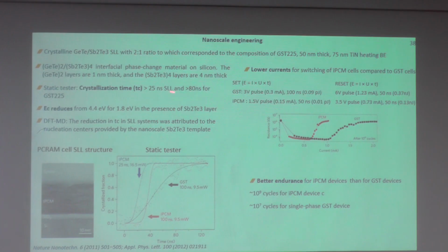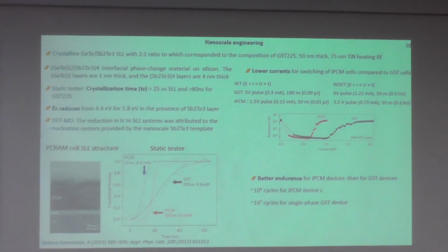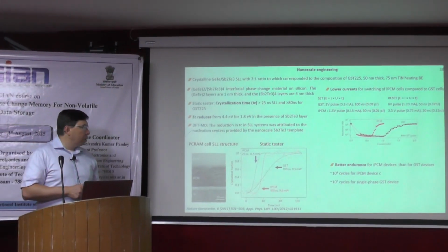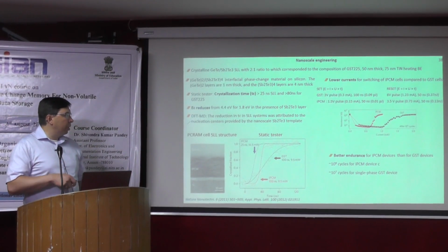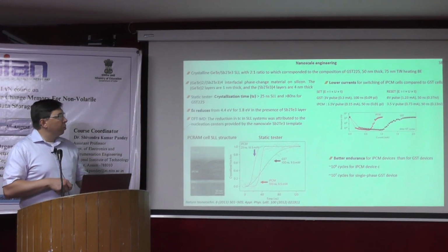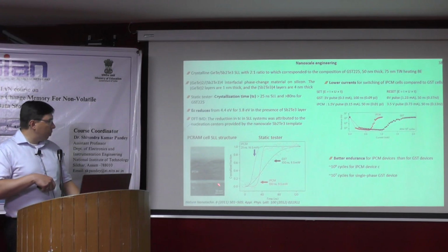The crystallization time is lower than that of GST225, but still on a nanosecond time scale and not sub-nanosecond. But here we can reduce the energy consumption. Also, we can improve the cycling endurance here. And it was one of the first works.